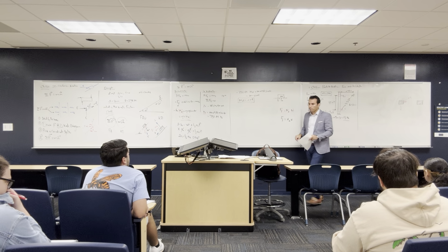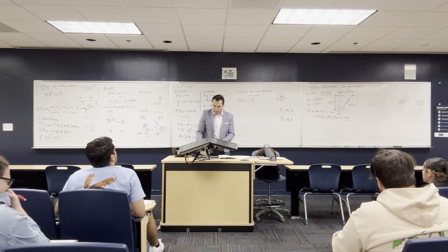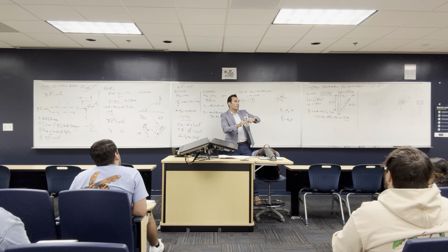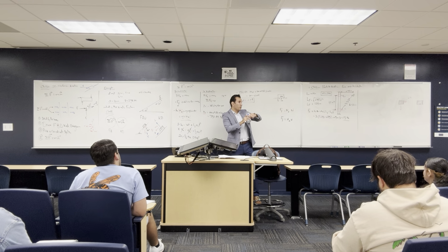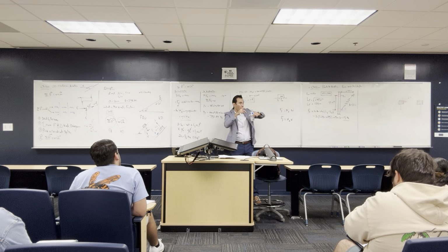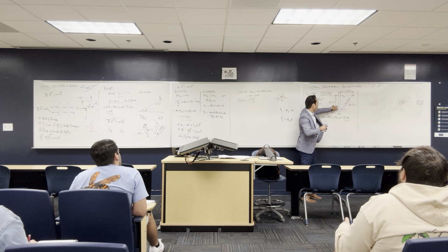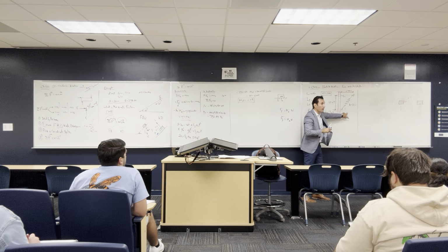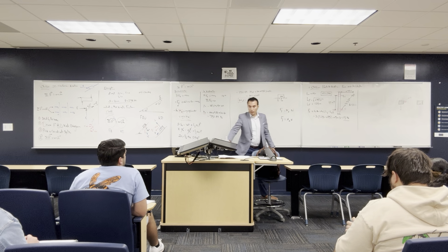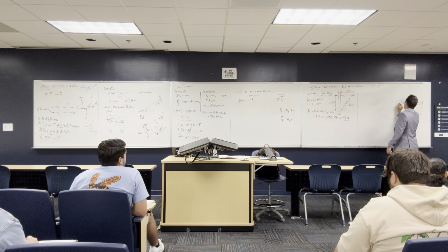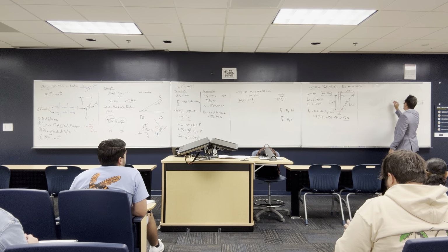Let's say you are trying to grab this out of my hand, but my hand is grabbing the other way. That's the same thing with the collar. This is pulling that way, my hand is pulling that way, but rather than my hand, the bar has a normal force on this so that it doesn't leave the bar. Okay? So this normal force is something like this, perpendicular to the surface. And that's all the forces on this body.